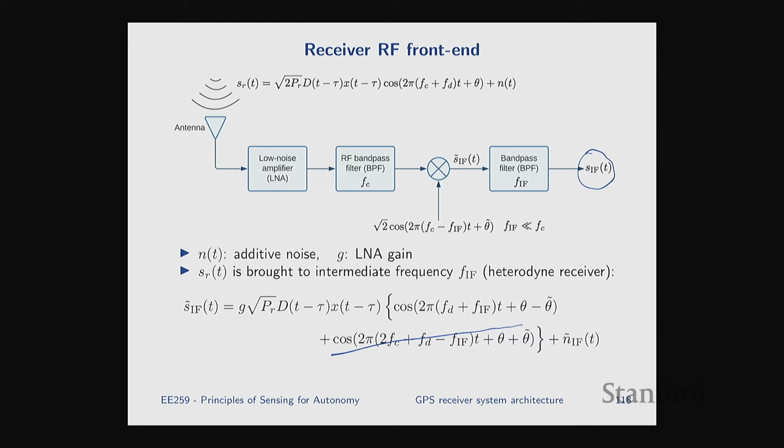Can't you just make the theta on the signal be relative to the oscillator? You can, yes. Maybe that's a better choice. But I want it to be more explicit in what's phase locked and what's not, so I'm intentionally adding the two thetas. But you're absolutely right. Mathematically, you can just say theta is relative to my LO and make this 0. Perfectly fine.